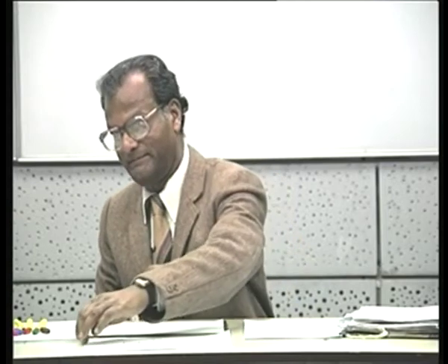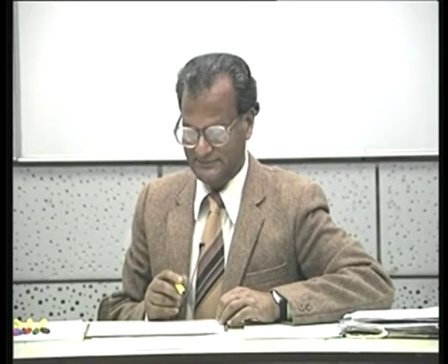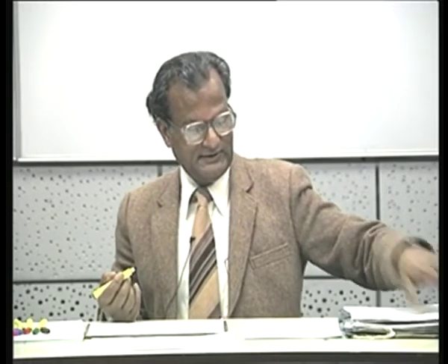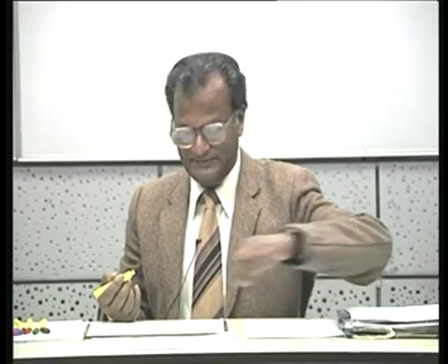Okay? So if for a network we find H21 is equal to minus H12, then we can say that it is reciprocal. It is a necessary as well as sufficient condition. Yes, that is correct. In fact, this is a test for reciprocity. Okay. Let us take another example.